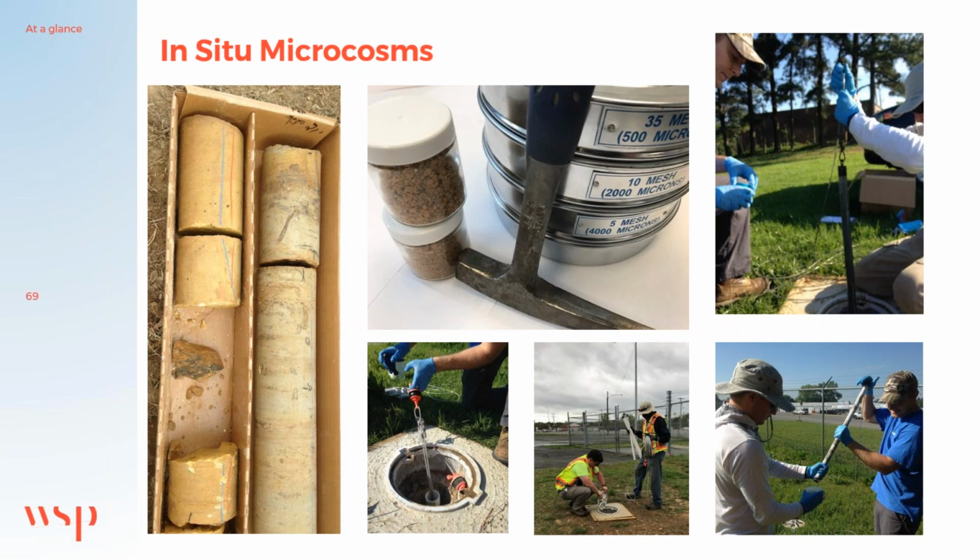Looking at the next question here is, how do you know the contaminants are degraded versus adsorbed and sequestered by liquid activated carbon? Well, that's part of the study, and we do so through the question I answered a few questions ago. We hope to get that data from the in situ microcosms that were deployed during the pilot test. So we'll look for isotopic degradation or isotopic fractionation to prove definitively that there's degradation going on. That data isn't in yet, but we do see sequential reduction to daughter products through hydrogenolysis.